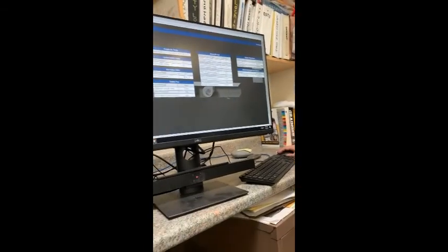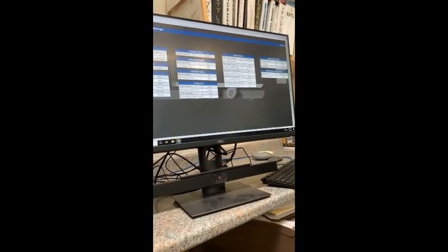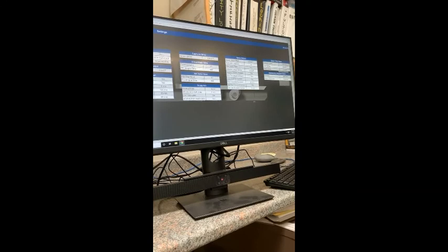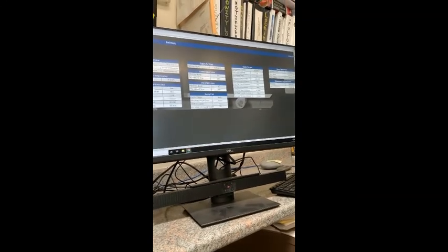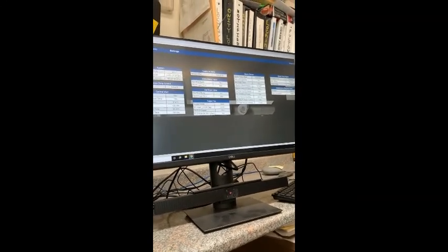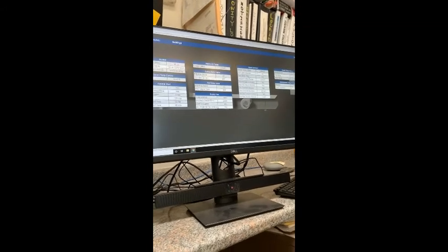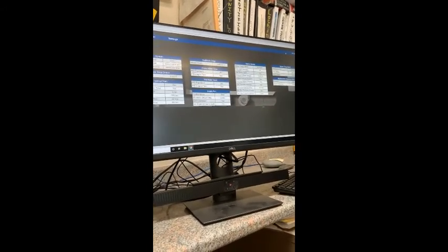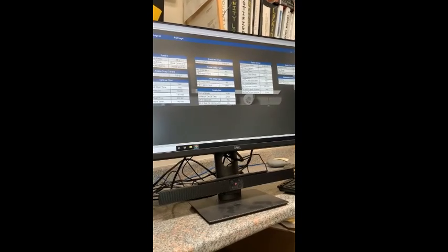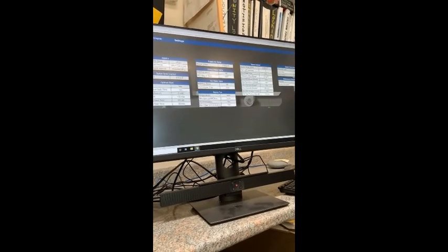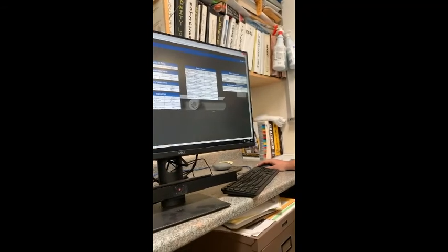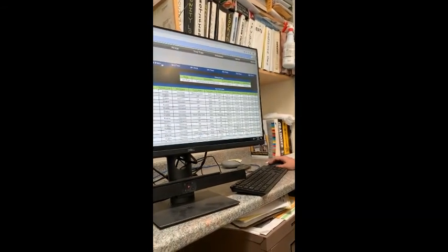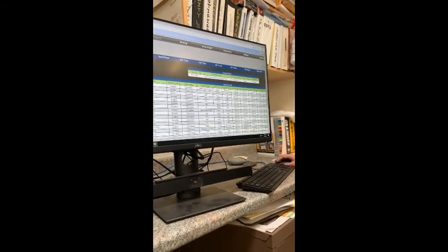And if we were to replace a water valve or anything on there, does it have to be learned to the system or will it automatically? No, as long as it's the right type of valve. These are all, I think, 0 to 10 volt DC modulating valves. They're not open or closed valves. They modulate to maintain a supply air temperature. The controller on each one would be a different story.